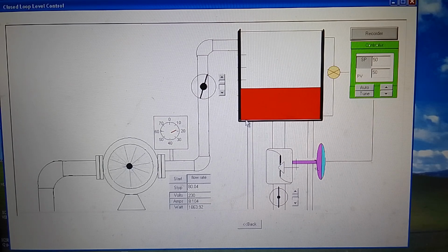So all these three operations cannot be done by two operators. Three operators will be required instead of two. So here it is automatic control. Only the automatic controller with the help of its transducer and control valve controls nice and smoothly.